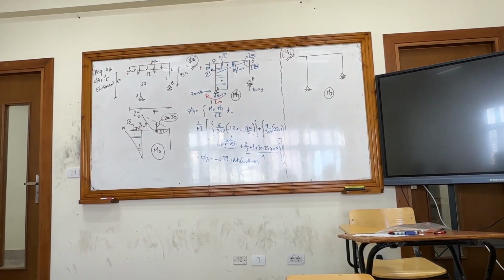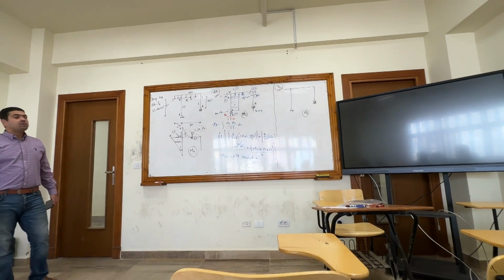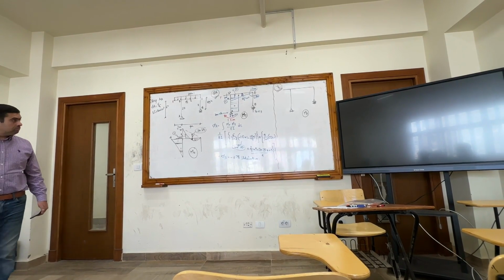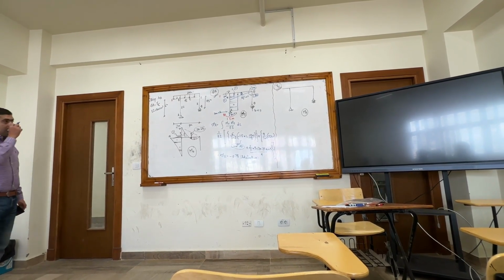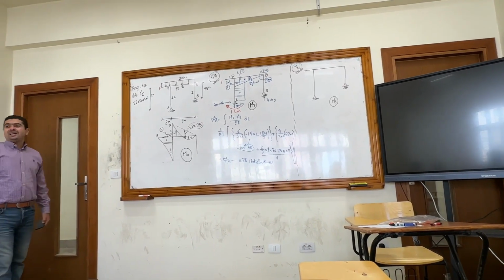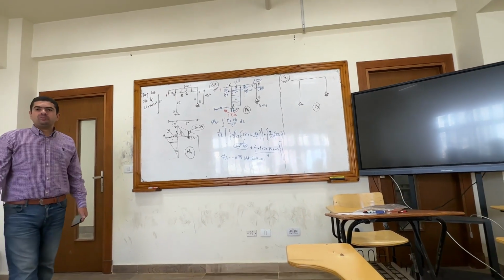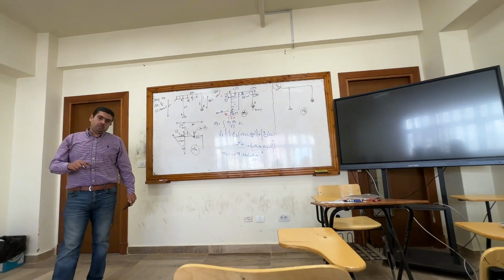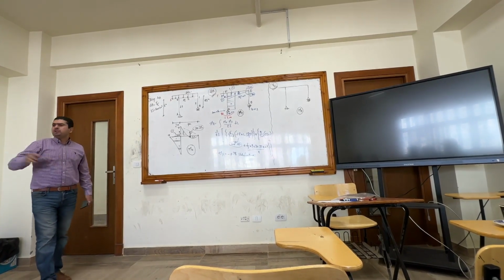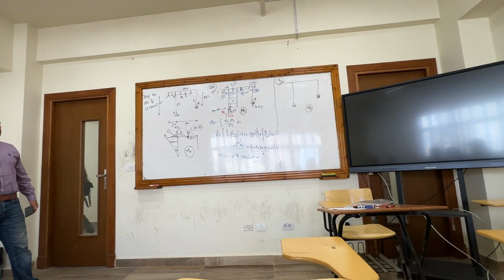The last requirement here was YC. YC means the vertical displacement at C, and you have to take care from this intentionally. Why? When I ask about any displacement inside a uniform distributed load, a vertical or a horizontal, I will not ask about rotation inside a distributed load.